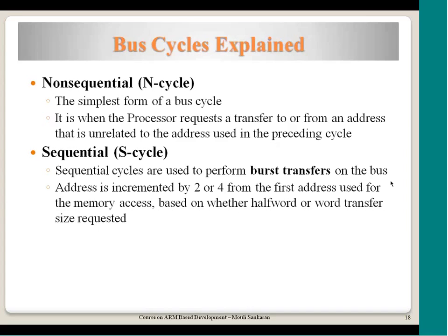So then you may wonder why half word is supported in the burst mode. It is because we may have a system where the memory that you are having in the system has only 16-bit data. The memory is a very cheap memory with a low cost application. So we can't say that an ARM CPU cannot work with a memory which has only 16-bit data.